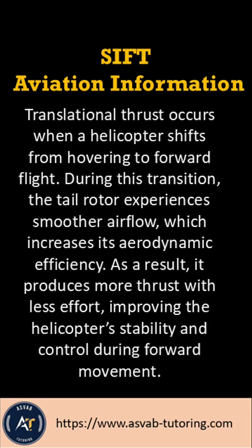Translational thrust occurs when a helicopter shifts from hovering to forward flight. During this transition, the tail rotor experiences smoother airflow, which increases its aerodynamic efficiency. As a result, it produces more thrust with less effort, improving the helicopter's stability and control during forward movement.